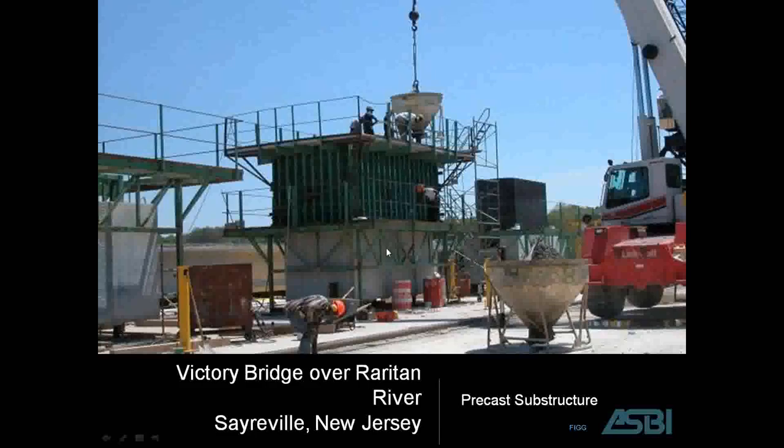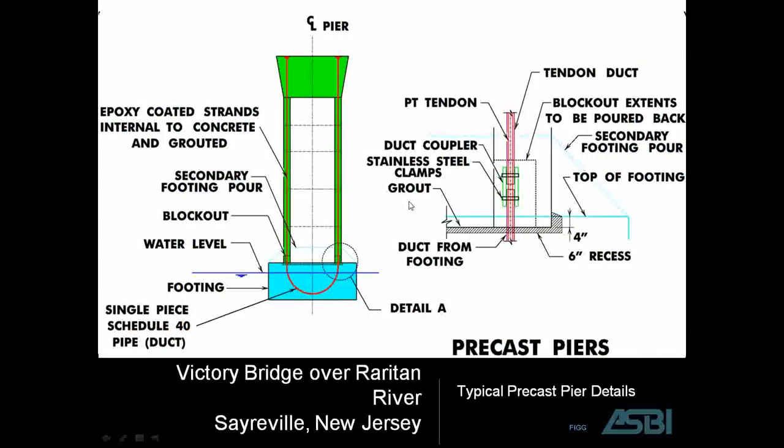It's lifted up. The segment on the bottom, which is the match cast segment, is placed into storage, and then the one that was the wet cast is set down into the match cast position. The forms are repositioned, reinforcing steel, etc., are placed, concrete placed, and it just repeats itself until each pier is complete. And geometry is controlled, once again, by orienting the segments to match the required geometry.